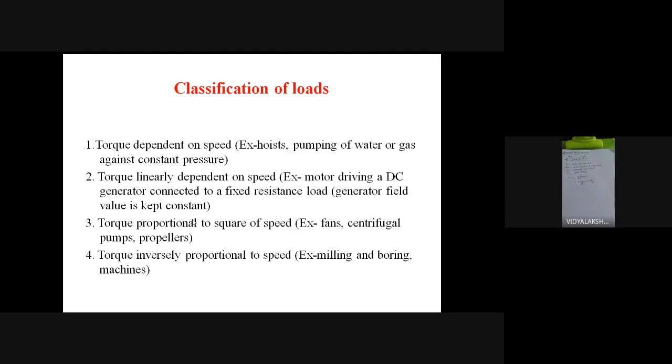The next one, so normally for constant inertia, I have chosen my dJ by dt equal to 0. So I take this term as 0, so it will be cancelled here. So my equation will be T minus TL is equal to J into d omega m by dt. I need my developed torque only, so it will be varying. It depends upon the TL and J into d omega m by dt. This is the fundamental torque equation of the drive. I'm repeating once again.